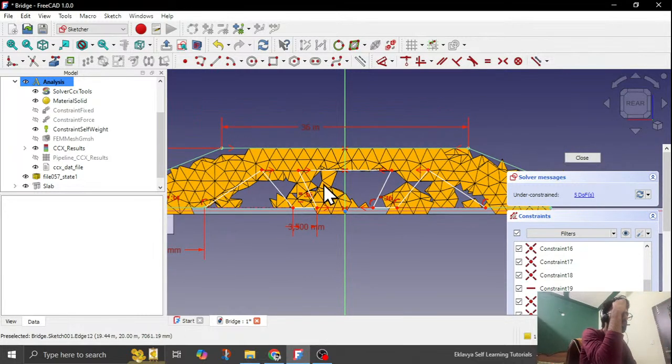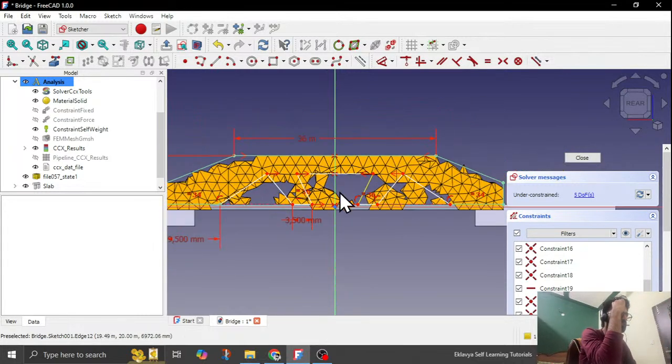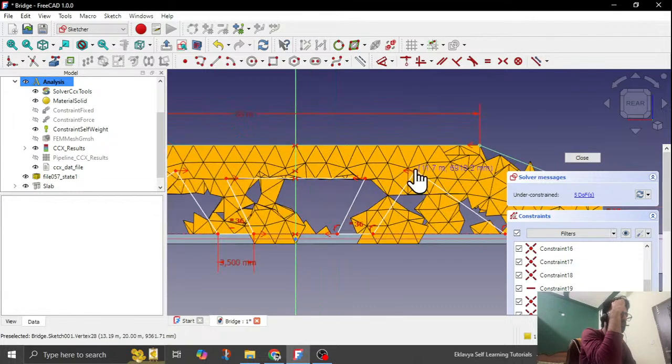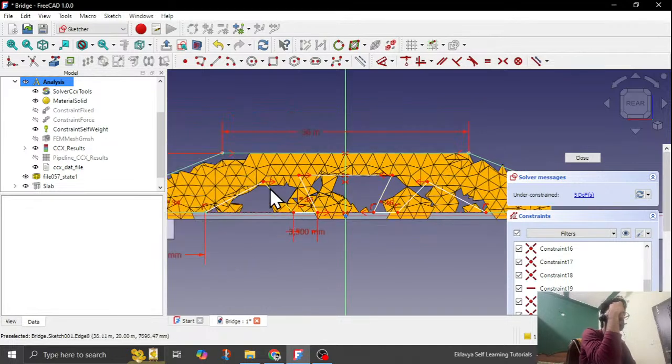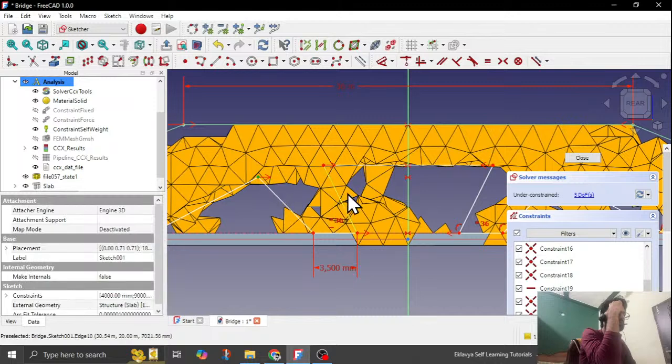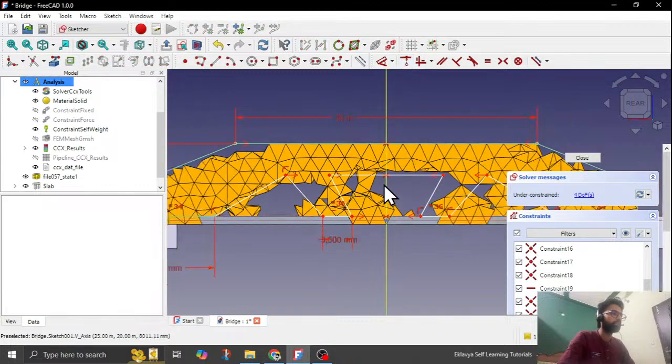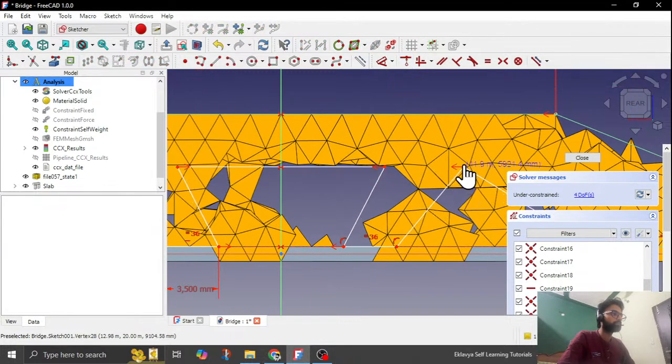Another length now in which we are interested in is these ones are left now, their heights. So how you can adjust their height is, it's very simple trick. Click on this point and then this line basically, guys, and simply click on constant constraint. Okay, same, this is already fine.